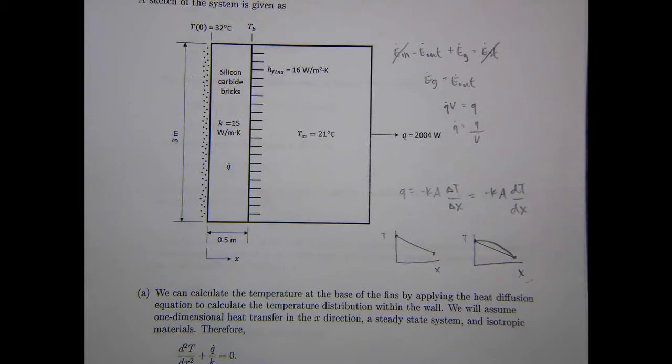And that's also what I was talking about if you worked the transient problem as just calculating the total energy in joules out and then dividing by the time. You're just assuming a linear rate of change of temperature with time. But in reality, it's more exponential.